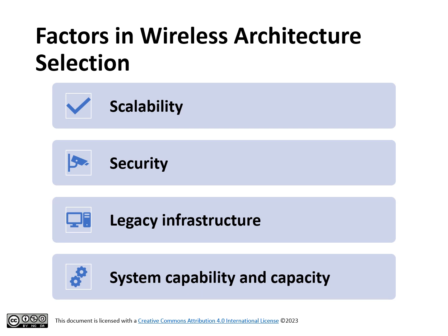It is important to adapt to the existing communication infrastructure to mitigate a costly transition or conversion. System capability and capacity. The capability and capacity of control system components to work with the proposed wireless technology must also be considered. For instance, the speed and bandwidth of the wireless protocol may not be appropriate to the operating requirements of the existing control system.